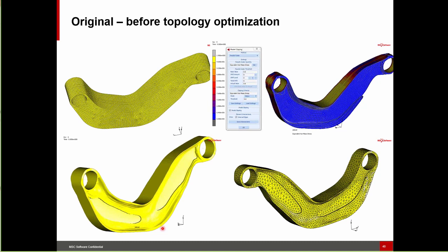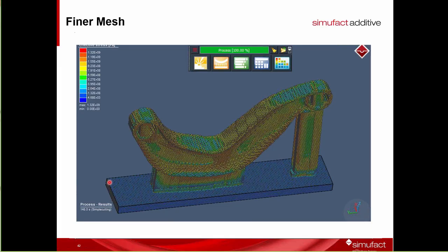It's very critical in this whole value of additive manufacturing because we can design new parts. So if we would have had a design space like this, we could have used MSC Nastran to tell us where we can remove material. We get information like this, which tells us that the material is to be removed. We have tools to basically smooth your geometry. We can then take that and generate finite element meshes for CAE analysis, or we can take the smoothed geometry and say, let's do additive manufacturing prediction.